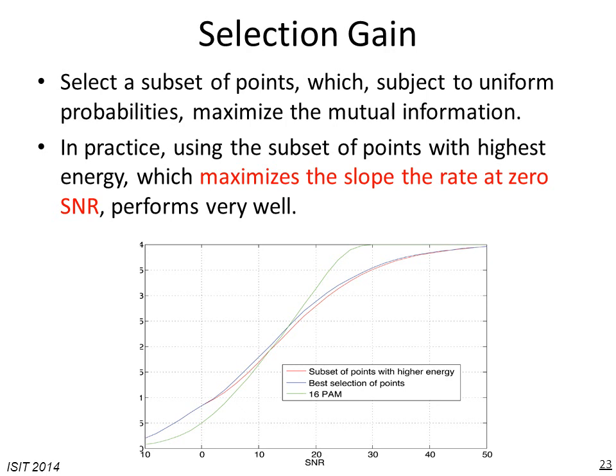For example, when the SNR is very low, it's to our best benefit to use a constellation with only 2 points, and we select those 2 points to be the points that are essentially furthest away from the origin, and we do the sign change, changing the sign of I and Q to embed the other information.